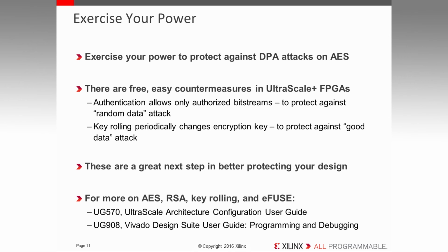Now you've seen how to enable DPA countermeasures to protect against attacks on AES bitstream encryption. These countermeasures are included in all UltraScale Plus FPGAs and are free and easy to use with eFuse keys. What we looked at today can also be used with UltraScale FPGAs in certain configuration modes. These DPA countermeasures are a great next step in better protecting your design, and I encourage you to consider using them in your next design.